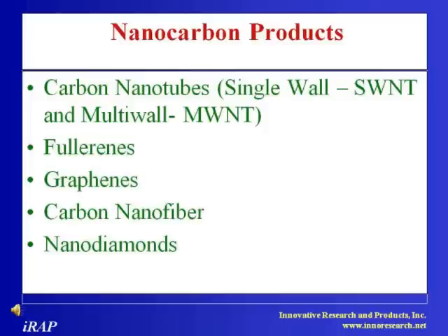Carbon nanotubes can be used in applications that include field emission devices, memory devices, that includes high density memory arrays, memory logic switching arrays, nano micro electromechanical devices, AFM imaging probes, distributed diagnostics sensors and strain sensors. Other key applications include thermal control materials, super strength and lightweight reinforcement and nanocomposites, EMI shielding materials, catalytic support, gas storage materials, high surface area electrodes, and lightweight conductor cable and wires.